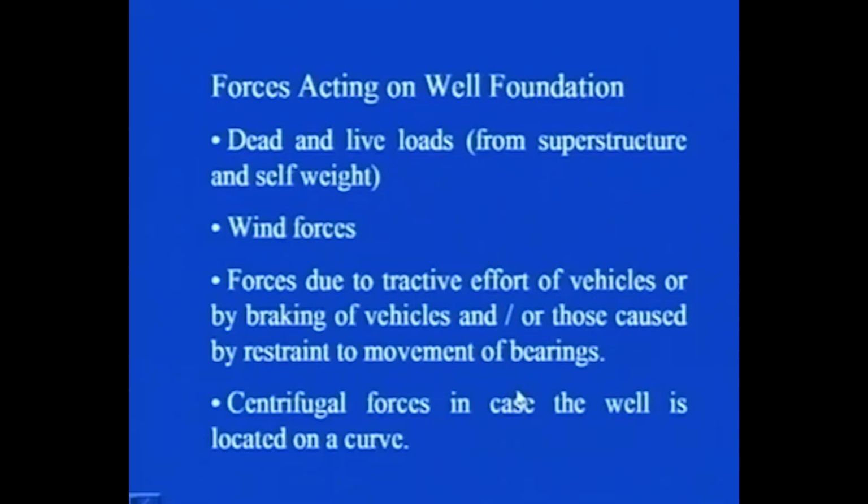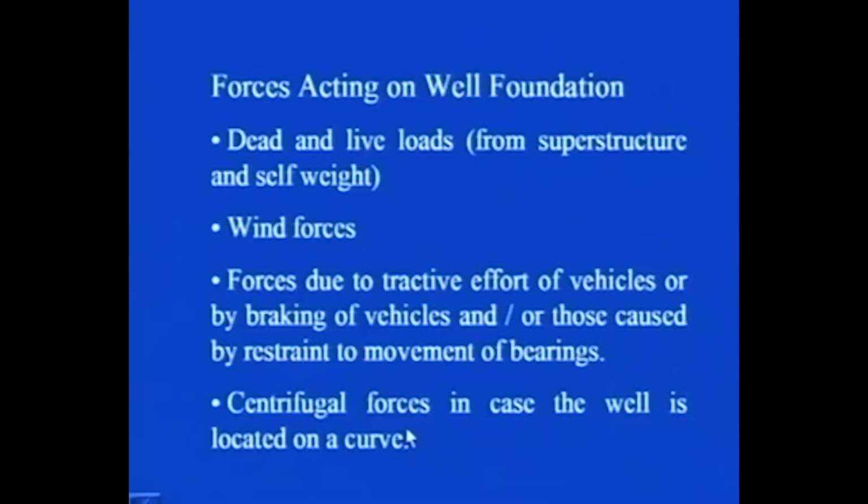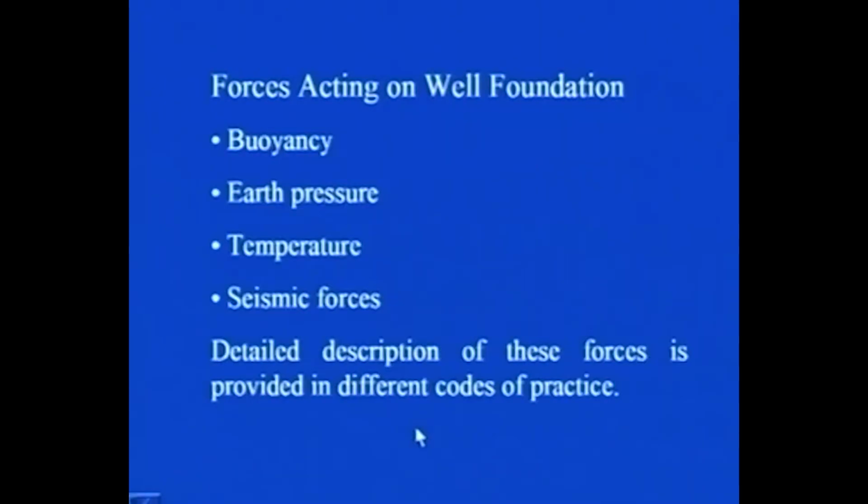The bridge for which it has been constructed, let us say that you are using it mainly for transport purposes. So, the forces due to the tractive effort of different vehicles will come into the picture. Now, in case the well is located on a curve, the centrifugal force will come into the picture. Further, due to the presence of water, buoyancy force will come. Further, earth pressure will come on the well foundation.